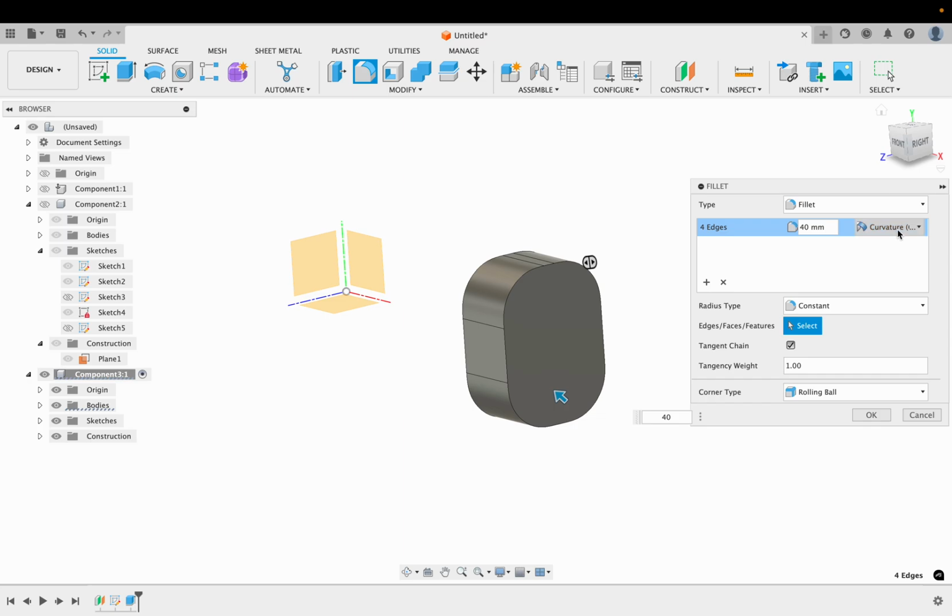The difference between tangent and curvature continuous is that on a tangent fillet you'll just have a straight line, and then it turns into a curve of straight radius and then back to a straight line. If you do curvature continuous, it's sort of like driving on a road. When you come to a turn, if you're doing tangent, you just flip your steering wheel over and then you flip back. On curvature continuous, you very easily turn in and then you turn out. I think the derivative is continuous on curvature continuous, which makes it look a bit more harmonic.